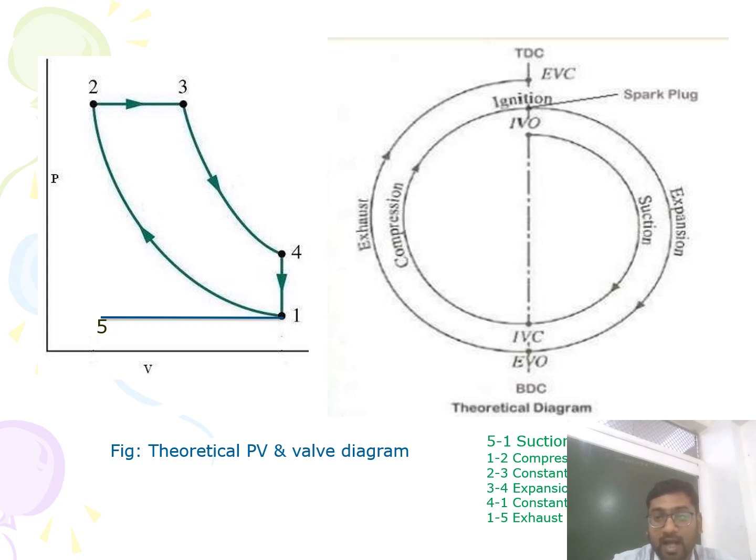It means the inlet valve is in the closed condition. So IVO to IVC occurs over exactly 180 degrees of crank revolution. The further 180 degrees of crank revolution is the compression process, as you can see in the figure, and at the TDC, at the end of the compression process, the fuel injector will inject and atomize the diesel, so that the combustion process occurs.